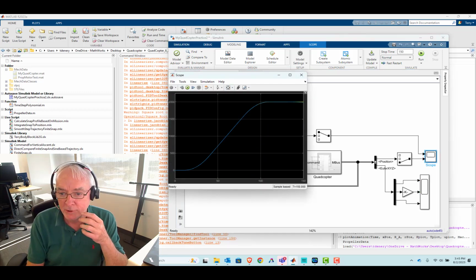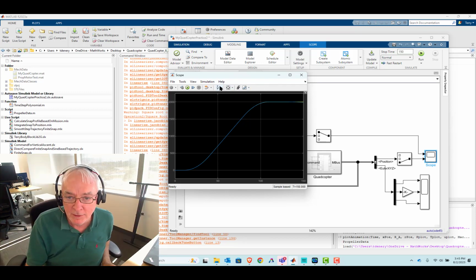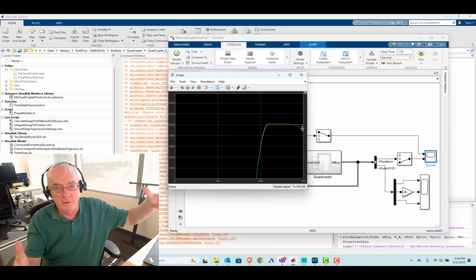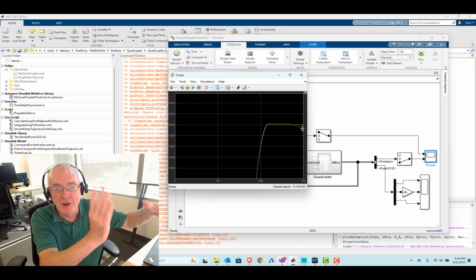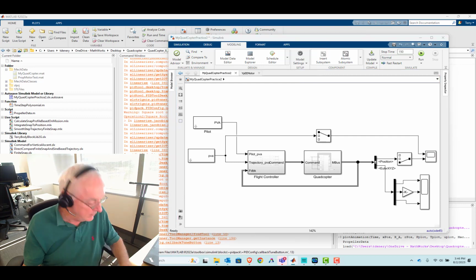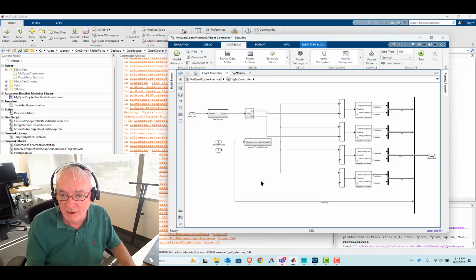We do have this opportunity. We've started rotating over 5 degrees, and we talked about it requiring a thrust adjustment. So let's see. Yeah, this is a good one. So we'll see how essentially the vertical position drops off. And that's really because we're losing a vertical component of thrust, and it's no longer enough to compensate for gravity. We showed the fix, I think, 2 videos ago, and so I'm going to just throw it in again.